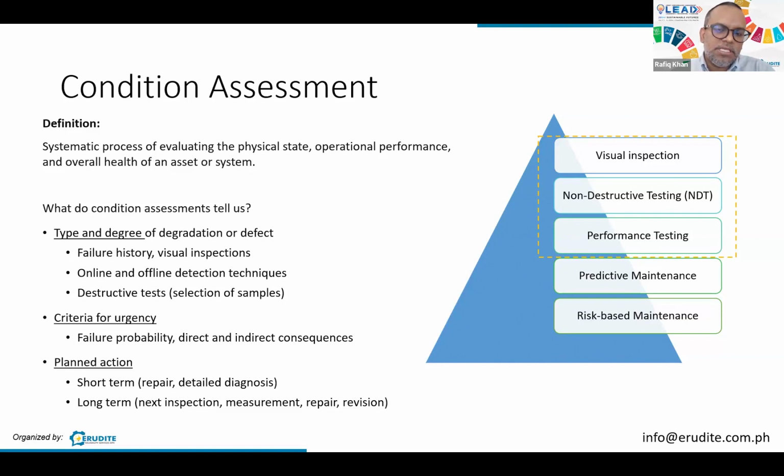Is it deviating from the intention of how it's supposed to operate? Are there signs of deterioration, damage, or wear? And what are the risks that we have with the current condition? If it goes on for, let's say, 5 years, can it survive? Will it fail? Will there be issues related to loss of life or breakdowns? What are the risks? What are the actions needed to maintain or improve the asset condition? So these are questions that we ask during condition assessment.